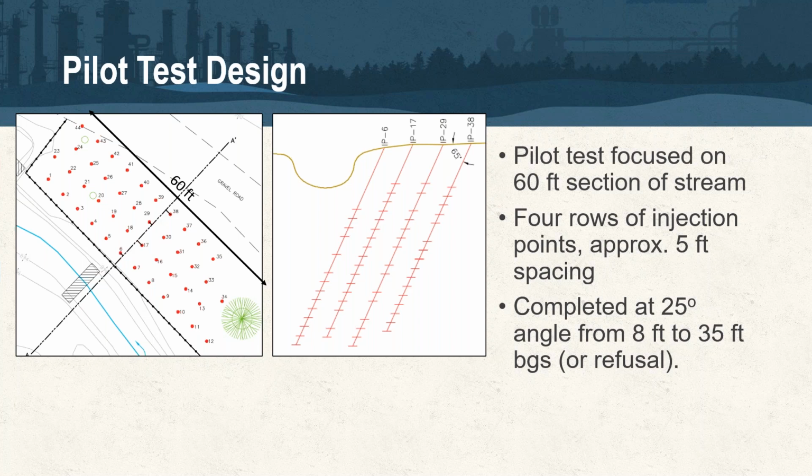The other thing is just, when you've got a very limited number of samples and you're trying to correlate that data, it's really difficult to do on most sites. And I think the folks that work with those tools every day would tell you the same thing, that it's really hard to correlate. You've got to kind of run those in parallel, and you can draw some correlations, I think, if you have a dense enough data set, but you can't go out on a site where you've done 2 weeks of MIP and grab 3 soil cores and a couple grab groundwater samples and expect to correlate that and come up with a remedial design.